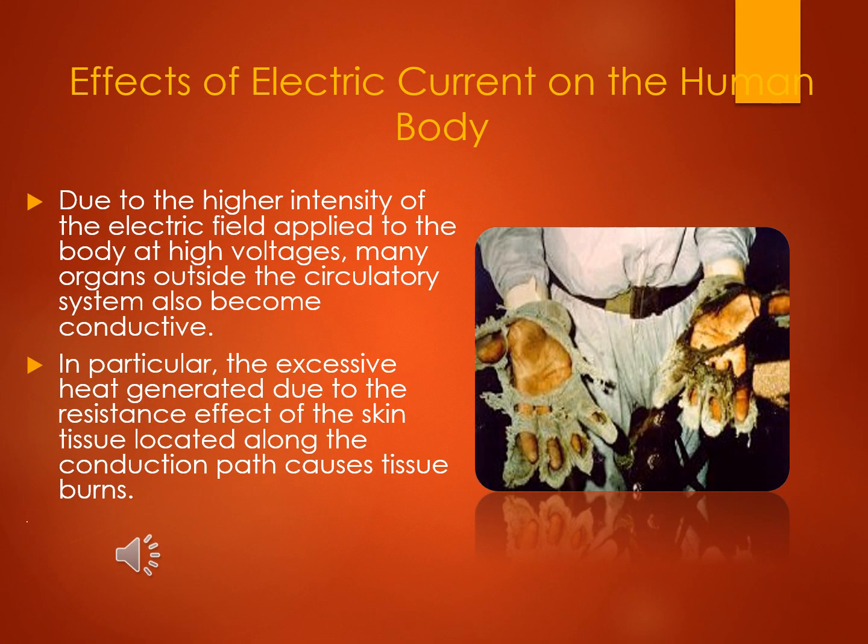Due to the higher intensity of the electric field applied to the body at high voltages, many organs outside the circulatory system also become conductive. In particular, the excessive heat generated due to the resistance effect of the skin tissue located along the conduction path causes tissue burns.